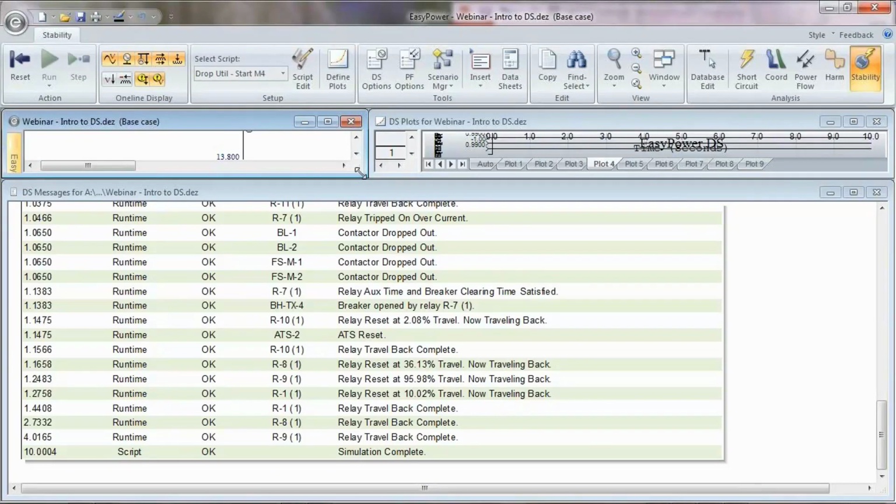Now, note here, you may not see this on a time current curve. Just understand, we are simulating the decay of currents in motors and generators in full detail. So you're going to see a lot more response. I mean, you might have actually seen a trip in a TCC, whereas here we're saying, well, we just squeaked under, or maybe we were a little better off than we thought.